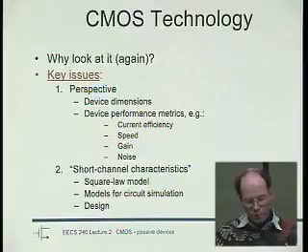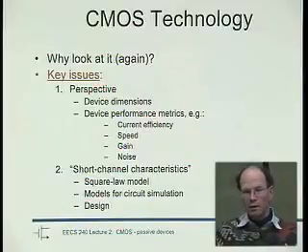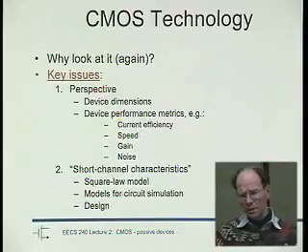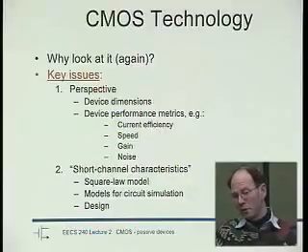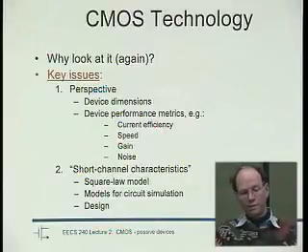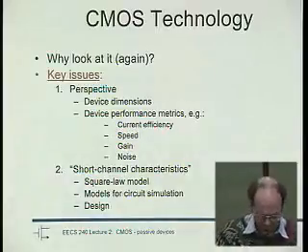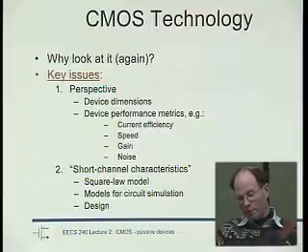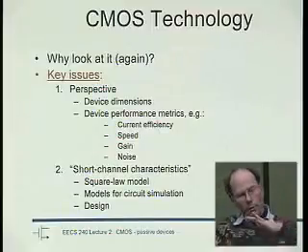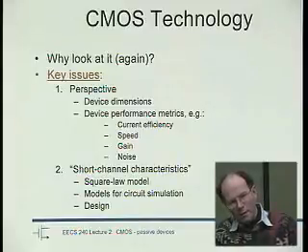And the reason, of course, or one of the reasons, if you haven't made mistakes, is this square law model is woefully inadequate if the channel length of the transistor is something less than a micron. And heck, I mean, when do we get the opportunity to use more than a micron, right? And actually, even if you use your 0.25 micron technology and make a transistor that is 5 micron long, then it still won't behave according to this square law model, because it was not only the channel length that was shrunk, but also the gate oxide that was shrunk.